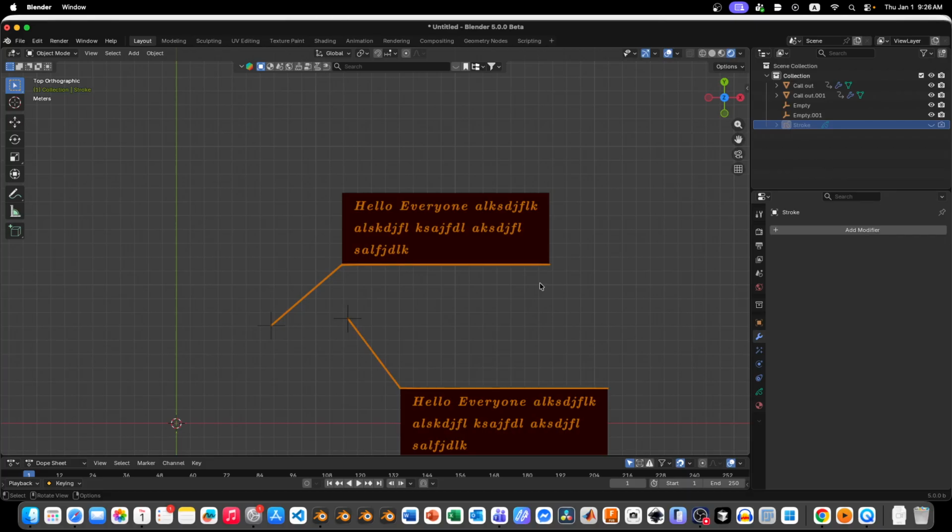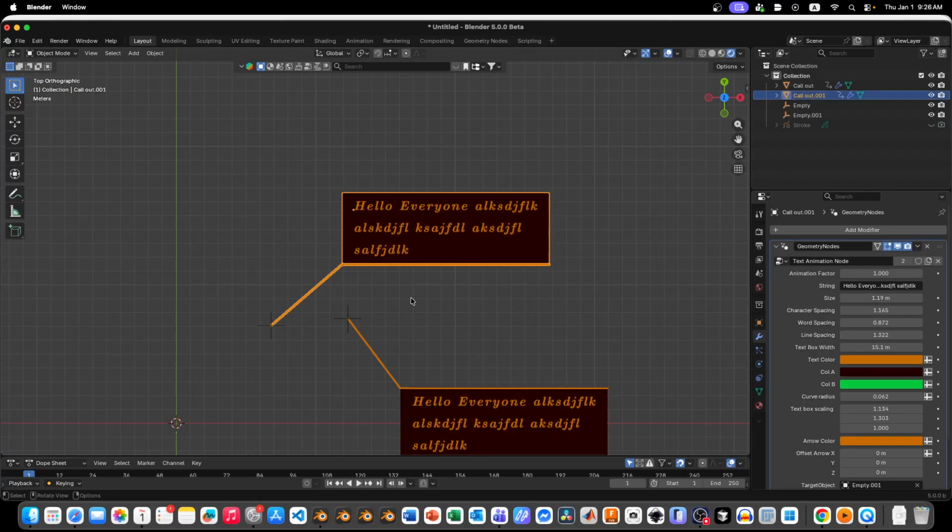You just need it to be in your scene, whether it is visible or not, and it will just have the information from the material so that you can have this arrow here. Because it is made with grease pencil, it is not affected by light, which is very suitable for a callout, which needs not to be affected by light. It needs to be visible all of the time, and it doesn't need any shadows. It just needs to be very visible for you during the animation.